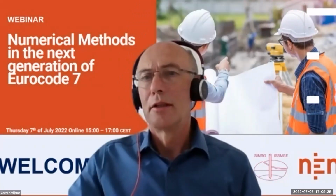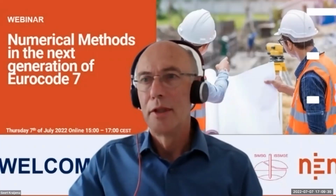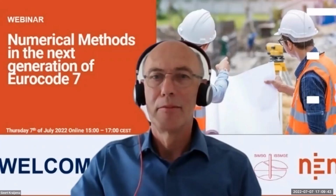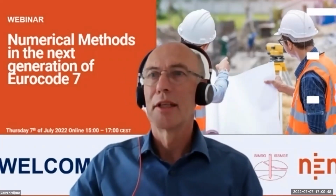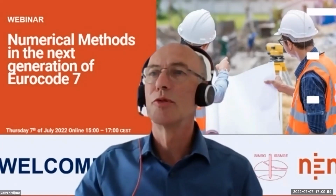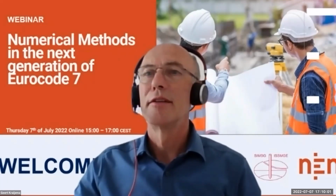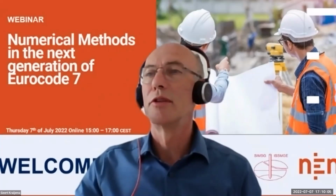Okay, thank you. For the audience, I think we will wrap up with those 4 questions now, because otherwise we are running too far out of time. So I will start with the question. In EC7 DA3 for slope design, if soil reinforcement such as soil nails is modeled in the slope, am I right that resistance factor set R1 shall be applied to the soil reinforcement?